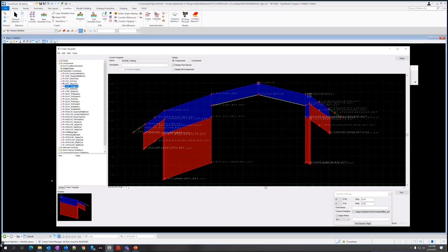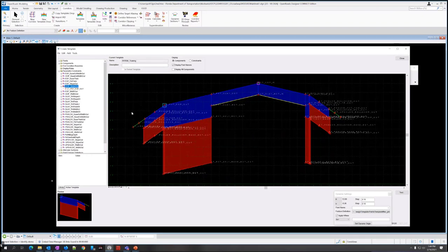So if I come over here, EOP slope out, when you select the point constraint or the parametric constraint, it'll tell you what it's referring to. So this one's actually negative EOP _slope out for the left side. So that's fine. I'm just going to double click on that parametric constraint and just change it right there. If you have anything that has the same parametric constraint, this will make it easier because then you can make the edit for multiple points at once.